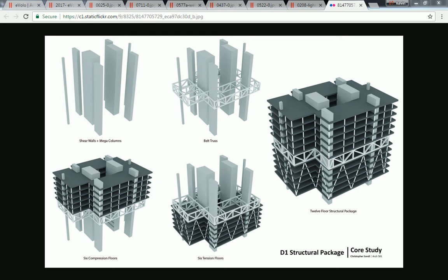So to give you just the 2-minute primer on structural megastructures like skyscraper systems, generally speaking, there are primary vertical elements, which are elevators and exit stairs, and then structural members like giant columns or trusses. Those are usually bound together by some kind of truss system or structural frame. In this case, it's a belt truss, and that's what you see in that diagram in the middle up top. And then from that, the floors are built, right?